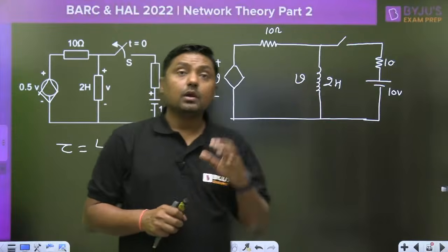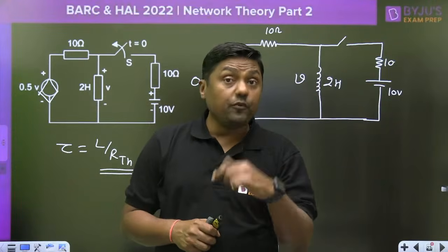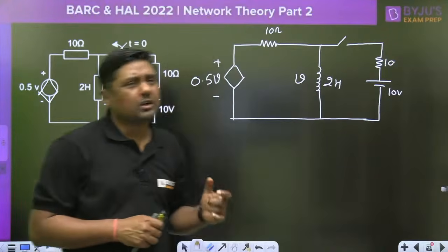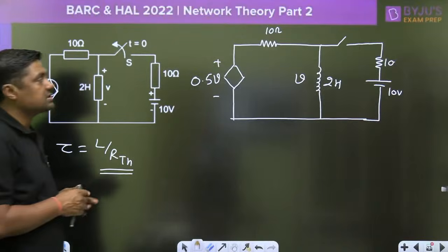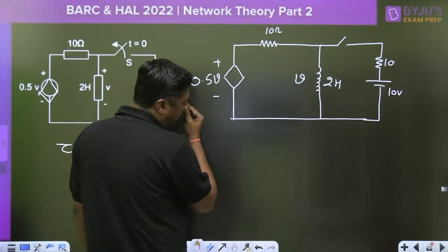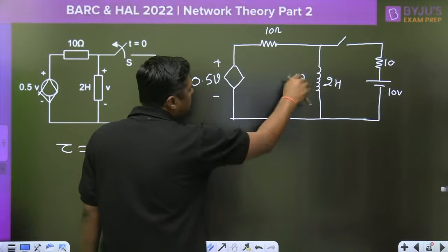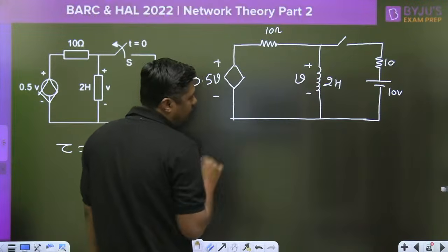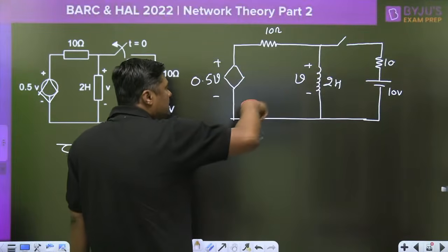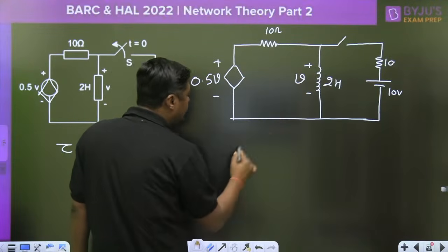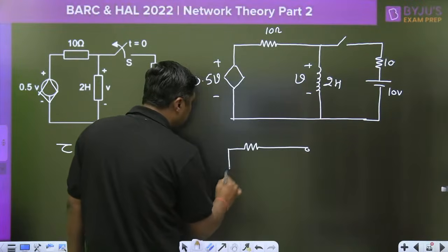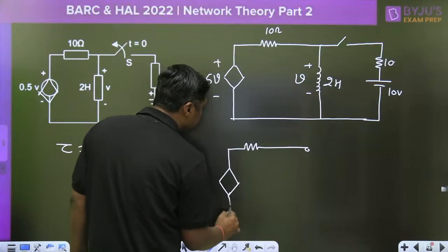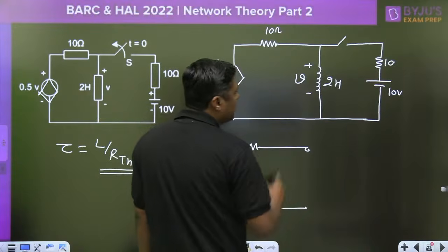If we are assuming that that is a dependent source, but I have given an independent source, you can solve it like this. If it is a 0.5 V dependent source, which depends upon this value, then my dear friends, always remember we have to calculate the RTH across this. This is the RTH, let this be the value.